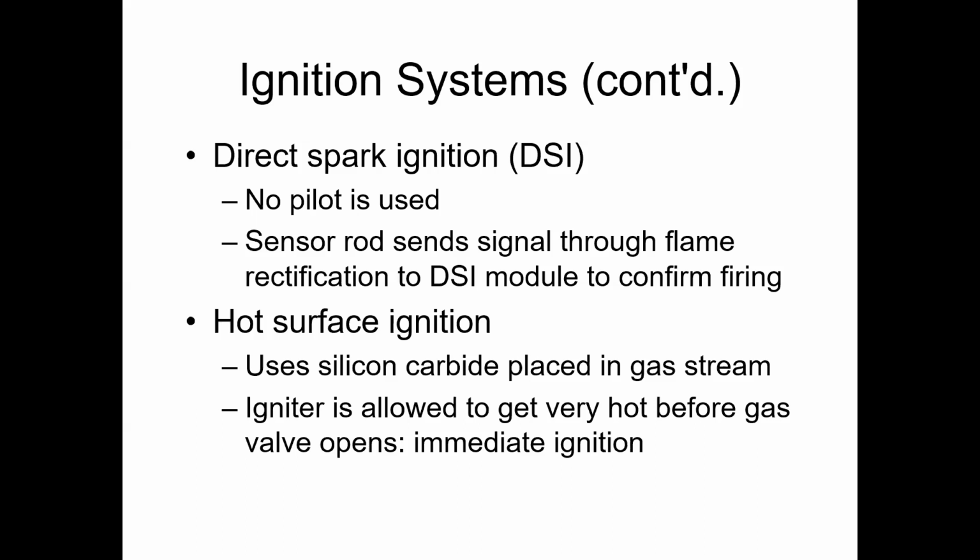These are really common to go bad. Hot surface igniters, I would say, are probably one of the number one things I tested residentially and replaced on a regular basis when it came to furnace repairs and furnace maintenance. It's a common thing. They're cheap. They cost maybe $15. Some of them, that's all it is.